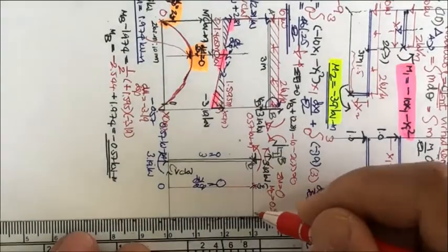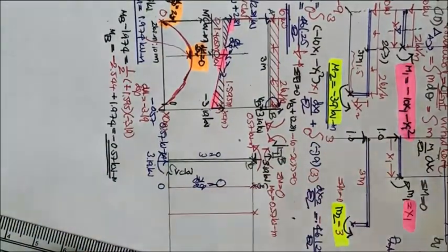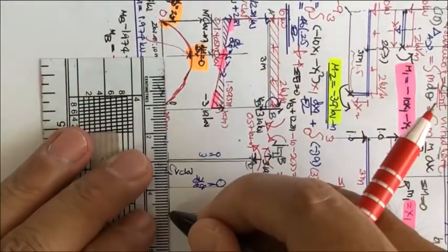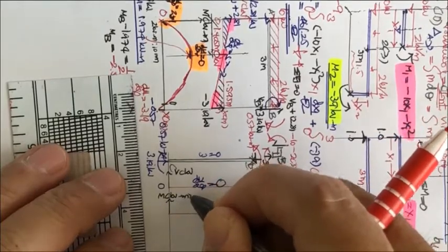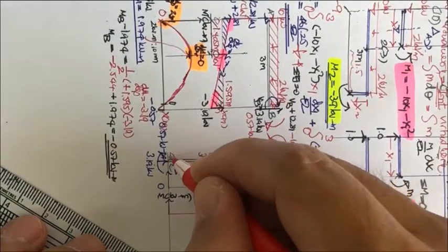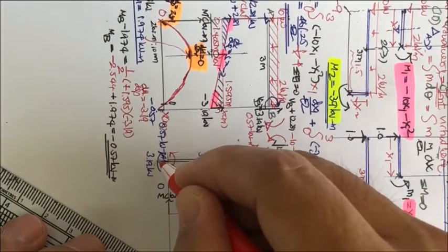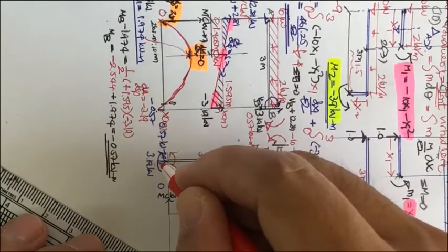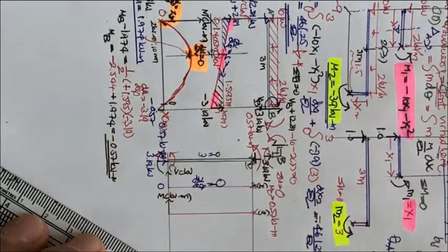Okay, and for the moment, again, this one is going to be x in meters, and this one is going to be M in kilonewton meters. What we have is this sign convention of M, and this one is in opposite. So our moment is going to be positive, since this one is the clockwise moment.